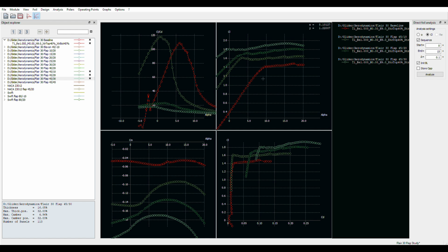And that would happen almost instantaneously. It would be equivalent to doing an accelerated stall on a regular glider, where you've pulled the nose way up and the speed bleeds off until all of a sudden it breaks into a stall. But he's done that by deploying the flap and shoved himself right into the other side of the stall curve. Stalls way back here at practically a 0 degree angle of attack with the flap down 30 degrees.